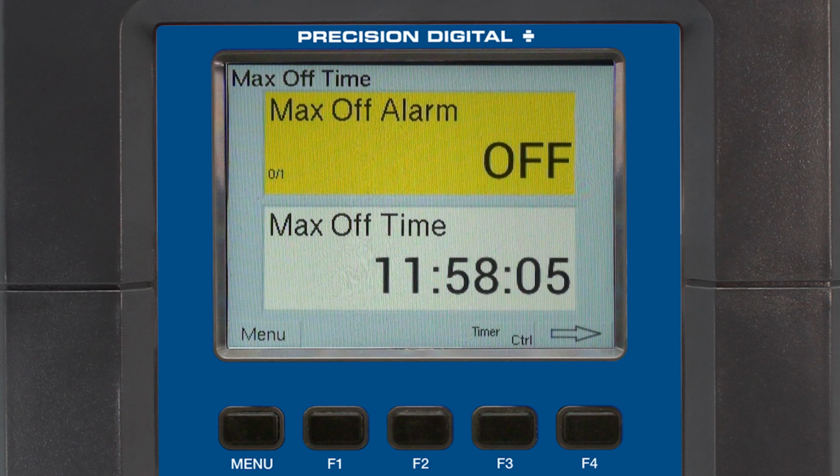Anytime a pump runs as part of normal operation, the timer stops. Once the pump stops, then the timer will reset and restart. This timer value is easily configured to any amount that may be desired by our user.